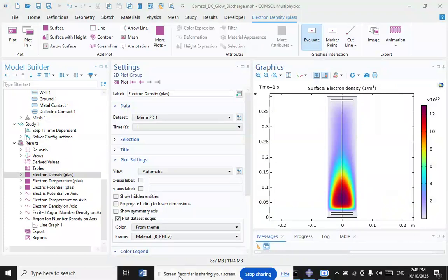The cell is typically filled with neon, but other gases can also be used. An electric potential of several hundred volts is applied between the two electrodes. A small fraction of the population of atoms within the cell is initially ionized through random processes, such as thermal collisions between atoms or by gamma rays.